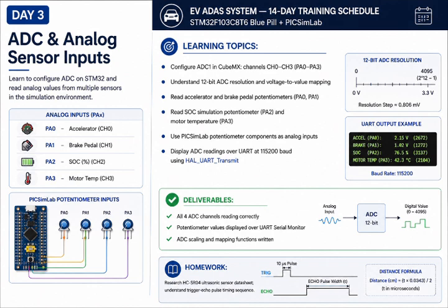And coming to day 3, I worked with the analog to digital converter. I configured ADC channels to read accelerator, brake, battery SOC, and motor temperature values. I learned how analog voltages are converted into digital values and displayed the sensor readings through UART communication. This was the foundation for collecting real-time vehicle data.